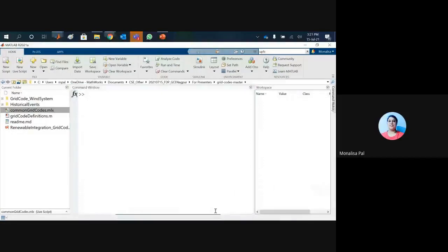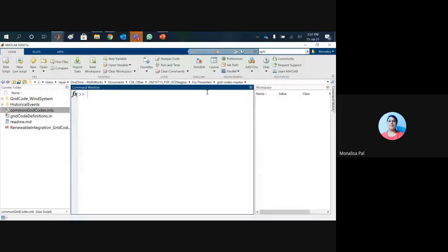Yes. Thank you. So this is the Matlab window that comes up when we launch Matlab. On the left hand side we have the current folder. On the right hand side we have the workspace. Whatever file is in the current folder, when we execute that, those files will execute, and when we save values, that would get saved in the current folder. On the top we have the ribbon. Various shortcuts are present over here. This is the command window.